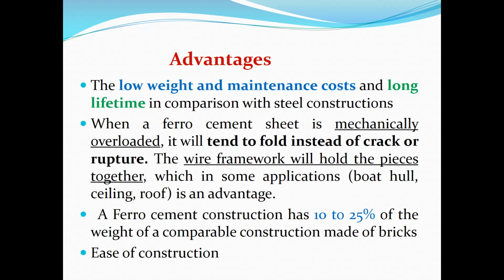When a ferrocement sheet is mechanically overloaded, it will tend to fold instead of crack or rupture. When overloaded, it will fold, because the framework, made with continuous wire, or closely spaced wire, or different layers of wire mesh, will hold the pieces together, which in some applications, for example a boat hull, is an advantage.